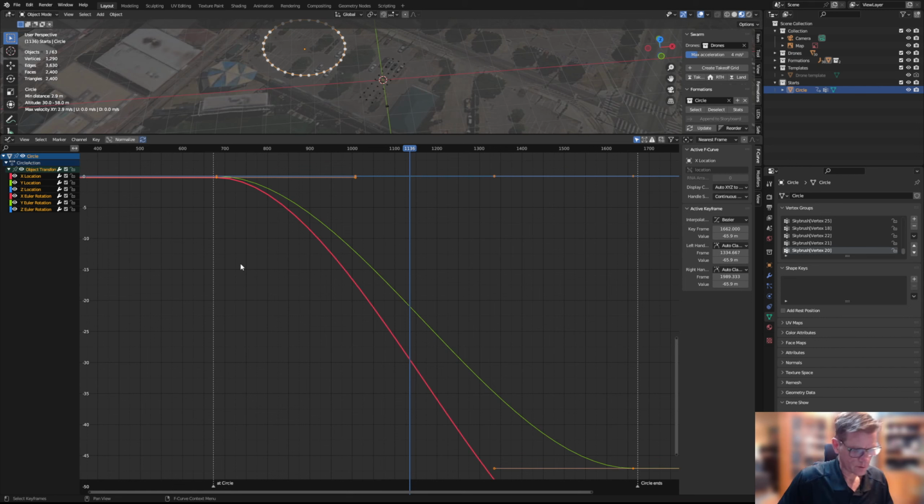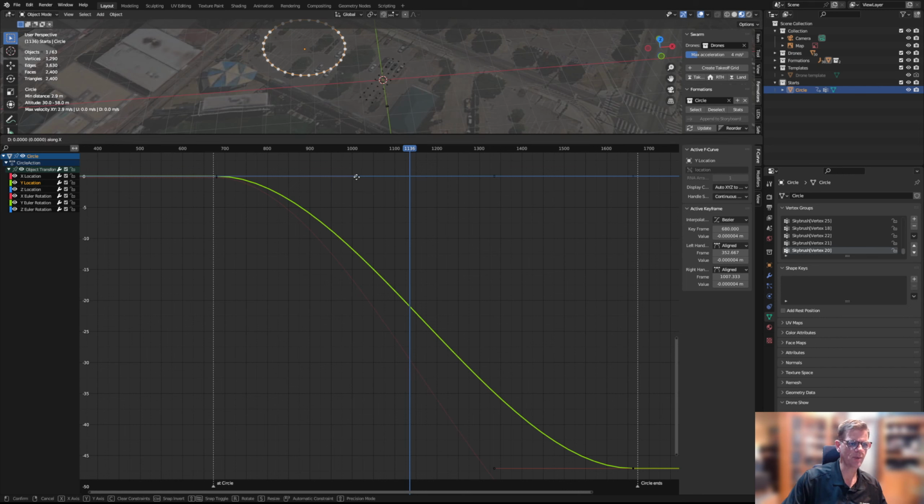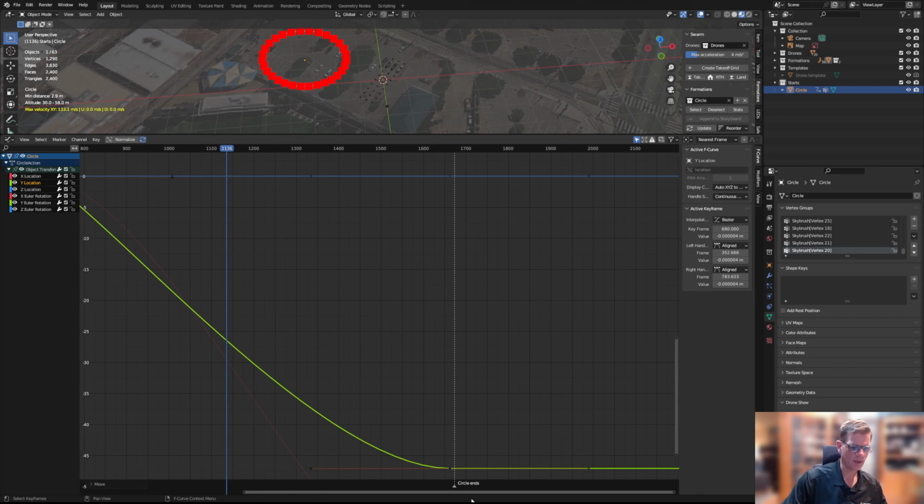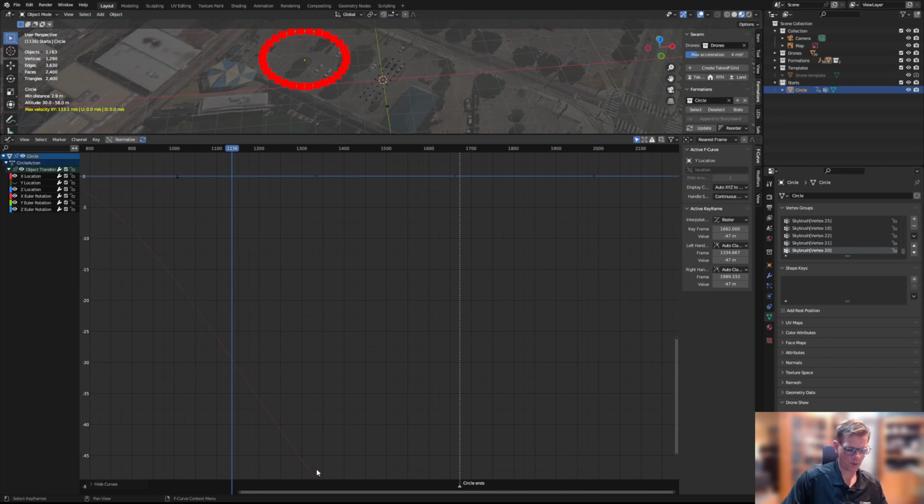So in order to reduce the amount of smoothing here that causes all that acceleration, select the curve that you want first, select the handle, and I hit the G and the X just to make sure I'm moving it purely in the X direction. By the way, you can really mess this up if you start moving it in an up and down direction. I'm going to go ahead and do that, move it on the back end as well.